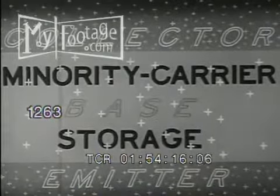The remainder eventually combine with electrons in the base to sustain the base current. They are minority carriers in the base, however, moving only because of their own thermal agitation. So it takes them a while to meet electrons, and quite a number of them accumulate in the base. This accumulation is called minority carrier storage.